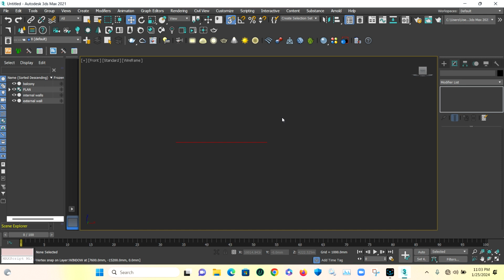Now, how I will calculate my height is using the normal block we use here. The height of the block is 225. Now, let's say your mortar height is 1 inch at the end of the day, which is 25 mm. At the end of the day, you have 250 per block. So bearing that in mind, I will use 250 mm per height of my block, so that it will be easy for me to calculate my block by number of courses. I can easily multiply it by 250.